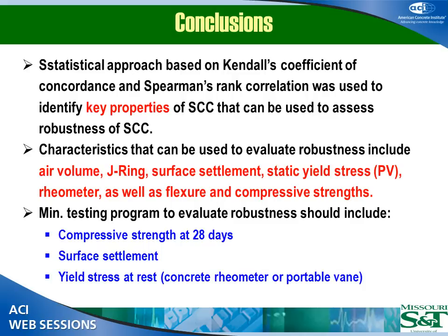But we've seen this in many studies, by the way. This is not the first time. We've done a lot of work using PNS and different types of PCEs. And in the industrial chair, we have 2 PhD theses looking at the effect of admixtures and combinations on rheology of flowable concrete. And it's always, we see this with the polycarboxylate, you get the stability, but in terms of robustness, they're more sensitive. It does not have to be related to viscosity, because some of them have higher viscosity, some of them have lower. But you're right, as you add more PNS, for example, that can reduce yield stress, but also can increase your viscosity. Thank you very much again, Kamal.